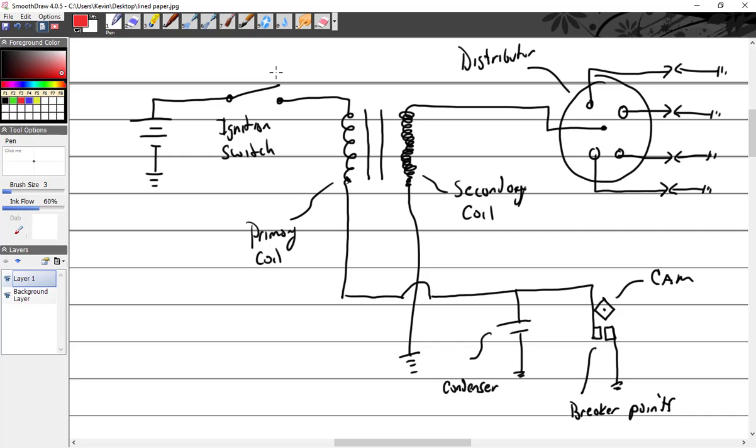And then somebody touches the propeller, and you've seen how slow it can go with that impulse coupling, right? Barely turns, and that impulse coupling snaps. What do you get? Spark. If there's any fuel at all in the cylinder, what's that going to do? There it goes. You can take a propeller and move it this fast, and if there's fuel in there, it is going to start and go. And it's going to chase you down.